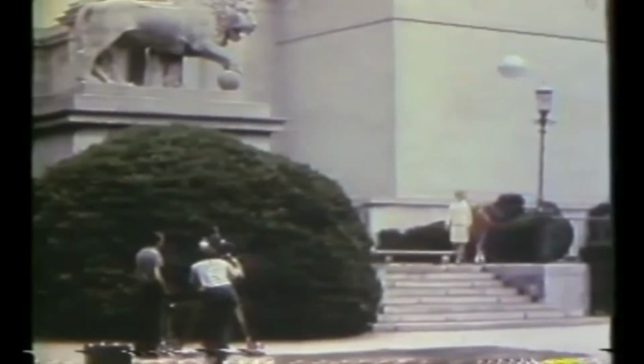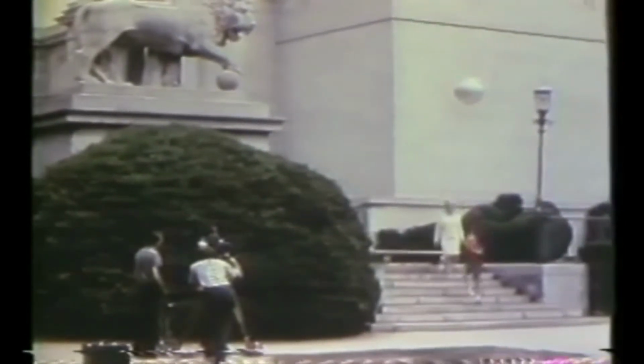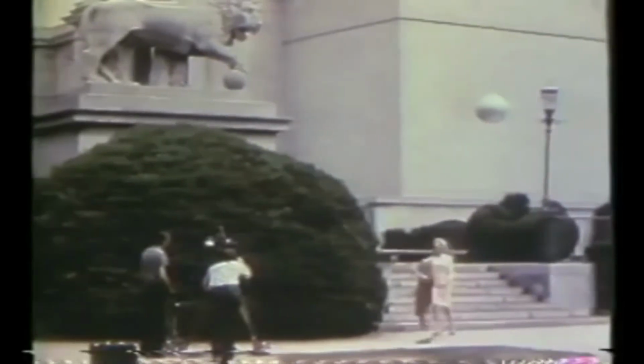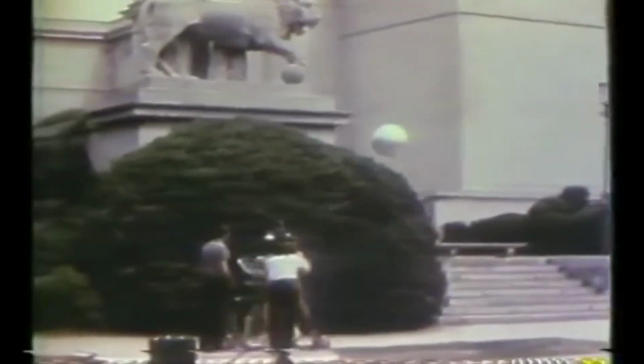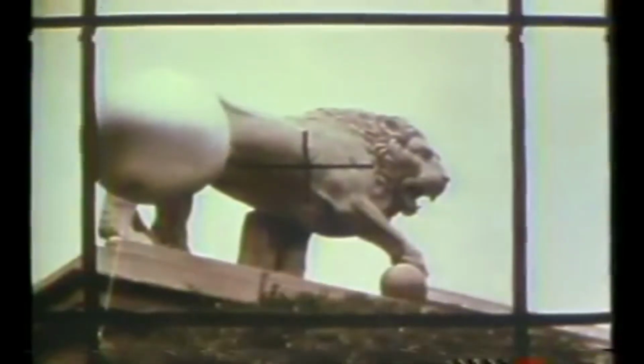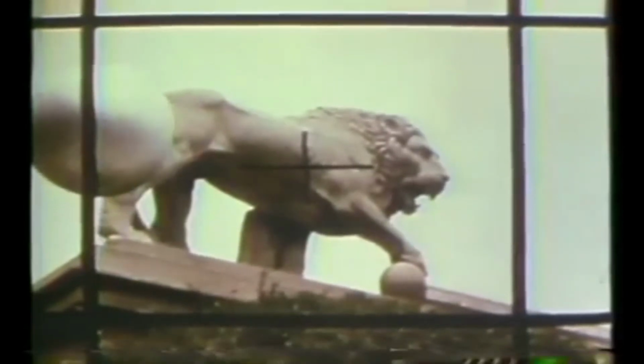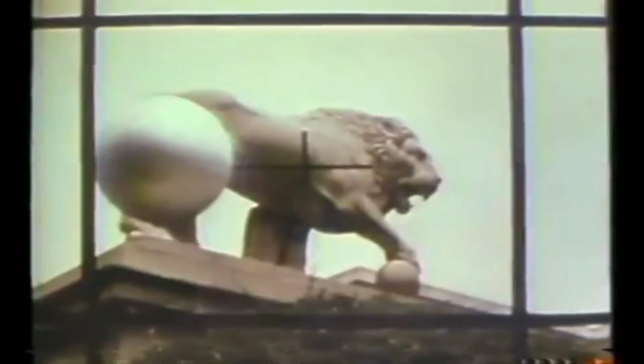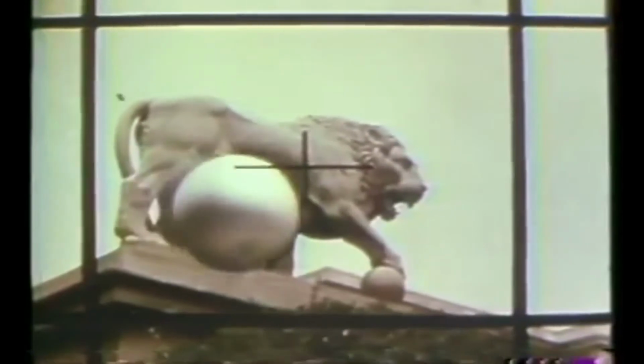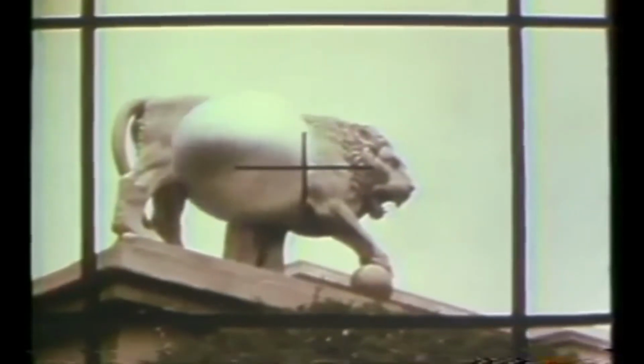One of the basic geometric principles of satellite triangulation lies in a phenomenon known as parallax, which may be demonstrated by a simple example. A fact of everyday familiarity to a person sighting past a nearby object toward a more distant background is that when his angle of view changes, so does the apparent position of the nearby object with respect to that background. A movement of the eye to the left results in an apparent displacement of the nearby object to the right.